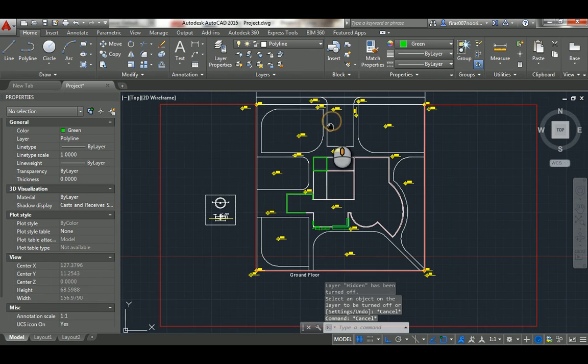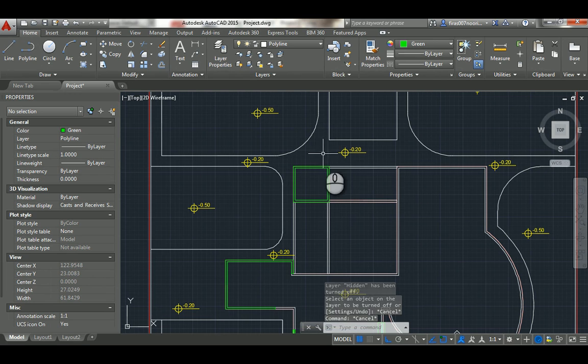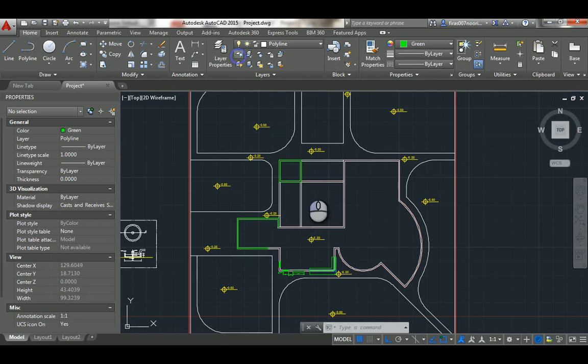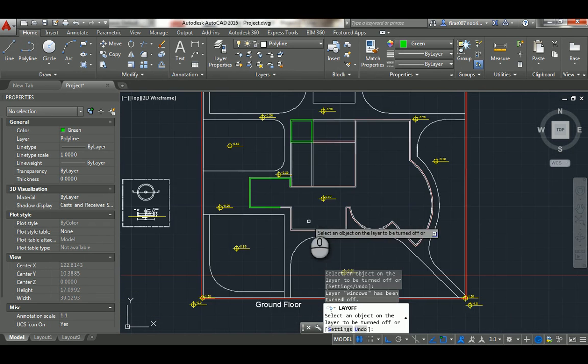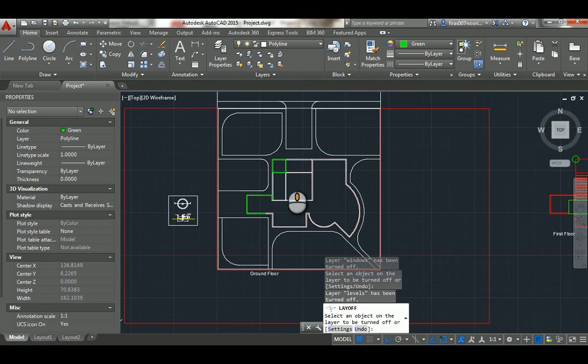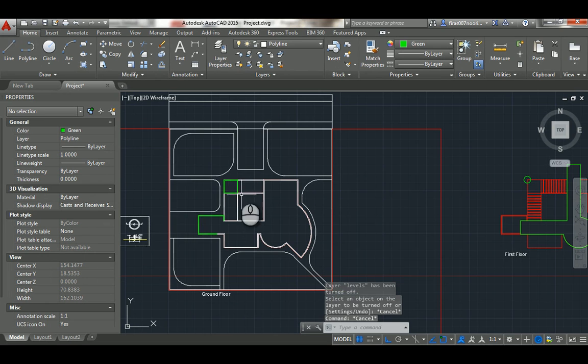As you can see, this is a kind of crazy walkway shape. This profile is located at -0.2. I usually give an extrude of -0.2 to all my horizontal surfaces except this one, because if you look at the provided difference for the level of the garden, it's -0.5, so that will make the extrude here -0.3 instead. Anyway, try to get rid of anything that might overlap with this, even the reference level itself.